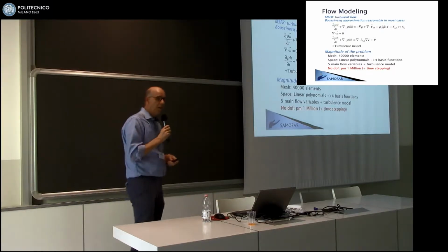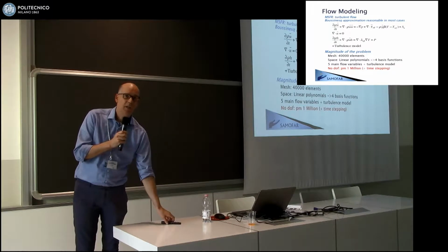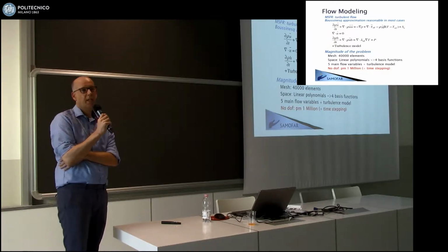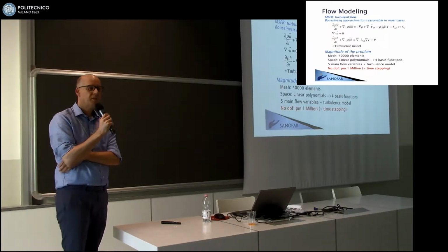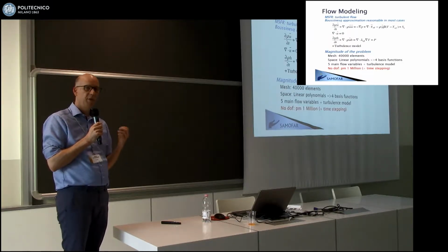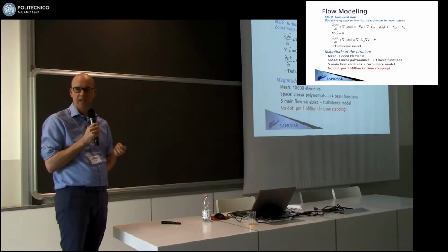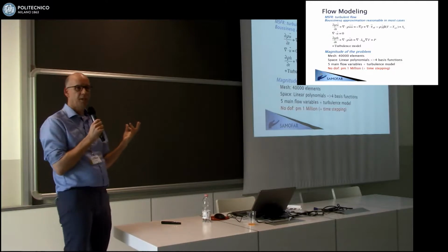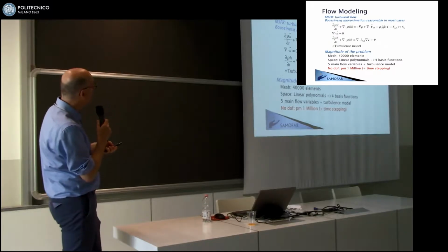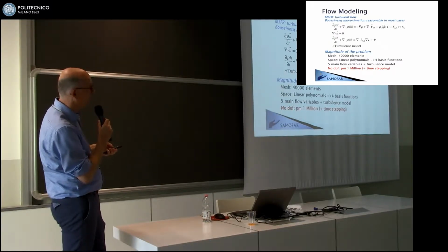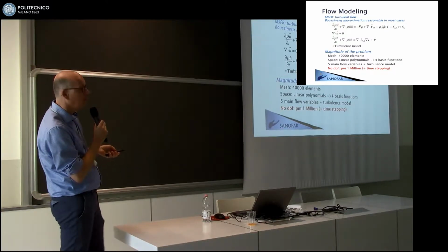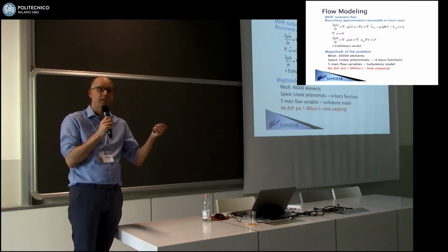Then flow modeling. Building upon what Pablo explained to you, most of the time we use Reynolds averaged Navier-Stokes modeling, which is essentially the cheapest option there is. This is a really big reactor with a very, very high Reynolds number. So you can just forget about doing a DNS or possibly also an LES for the whole system. So a RANS calculation would be the most sensible thing to do. Well, these are the RANS equations that Pablo already mentioned. And any turbulence model could of course be augmented with this. So it's maybe k-epsilon or k-omega or whatever.